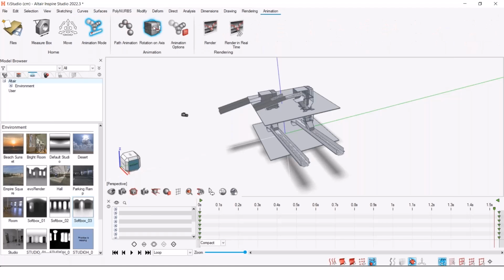And then in the animation, you define a path animation for this object along the path that would be the curve that you set up. And then the camera is going to follow, during the seconds of animation you actually have, the path that you have set and render the animation in that way. Hopefully that's an introduction to how you can do it. Hopefully it helps. There's always more that can be explored in that sense.